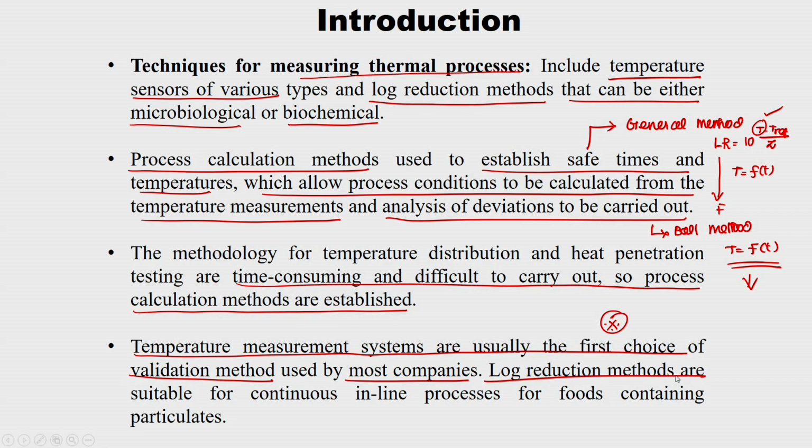And also, log reduction methods are suitable for continuous inline processes for foods containing particulates. Why is it? Because here the temperature measurement is done using a thermocouple. You cannot employ a thermocouple in a continuous process because it may hinder the process. The continuous process most of the time involves convection.